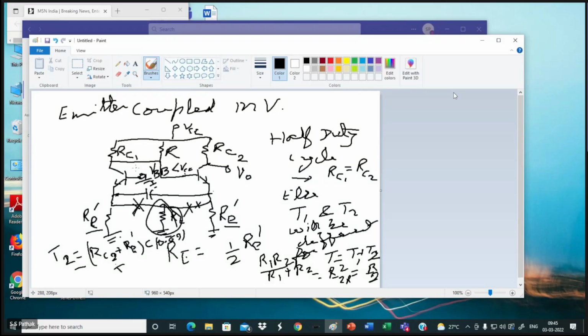This V gamma comes to this point, so this becomes your on. When this becomes on from active, it will be charging through this resistance, this on state, this capacitance, and this RE2. It will be charging the capacitor according to that. So this is giving you your T1.